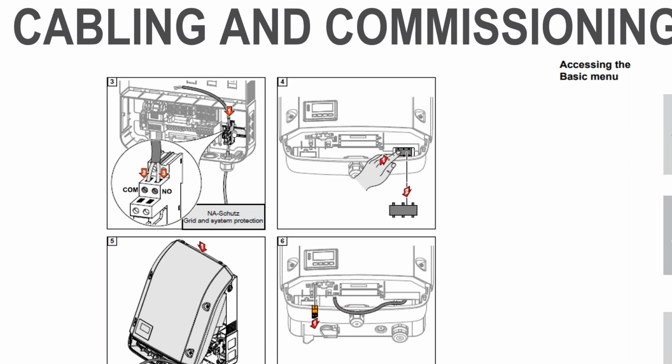Of course, you can have this relay installed on the DIN rail, as you can see, with the cables connected to the designated points, that is the common and the normally open. But once this connection is done, this cable would have to travel out to meet the S0 switch.